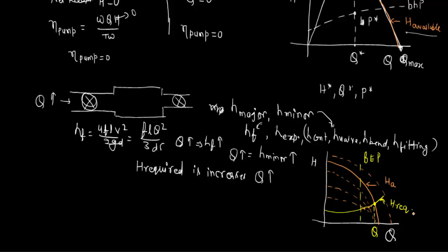For different RPM, obviously the curve will be different, so we can manipulate the values, find our requirement and adjust them, and if possible get the required or intersected value at the best efficiency point, which is the best case for the pumping system.